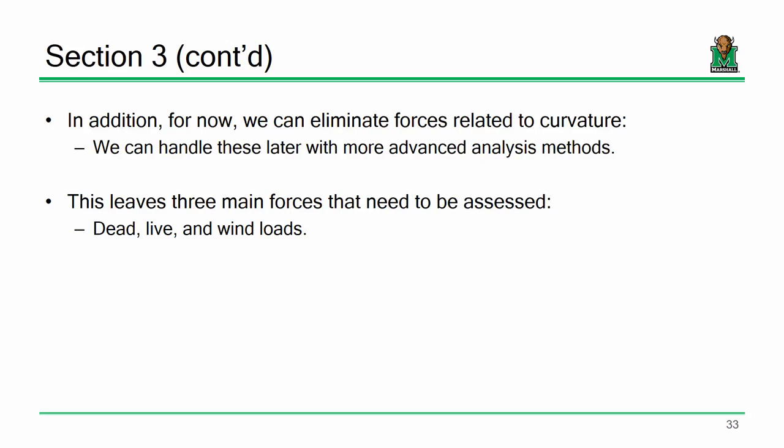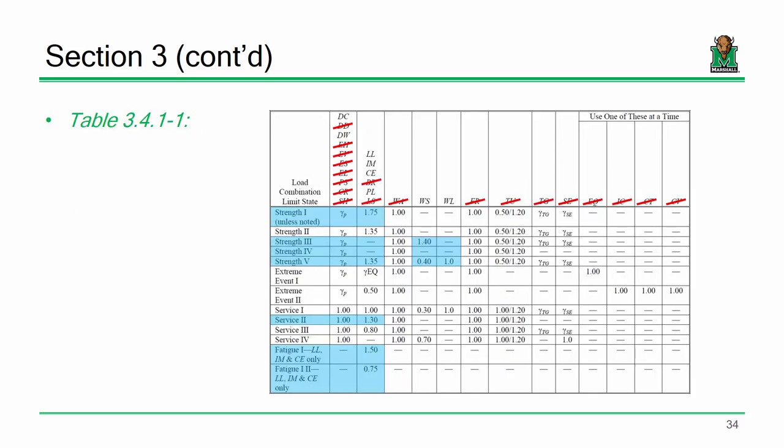That 64 pounds per square foot is way larger than any snow load we'd see around here with a ground snow load of 20 PSF. That's number one. Number two, typically we don't like our bridges to be deep in snow. We'd like to see them used. That's why you have trucks going all over the place, plowing them out and whatnot. All right, so what I've done here with this table is I way simplified it.